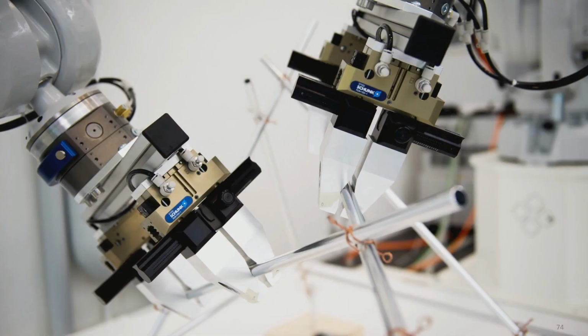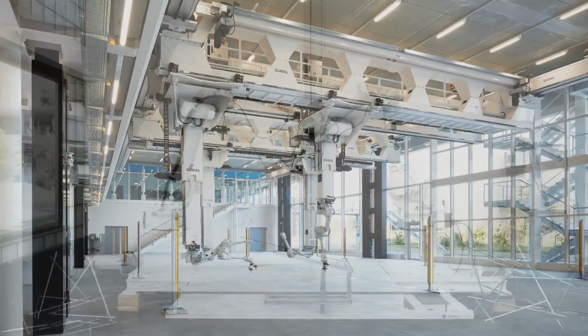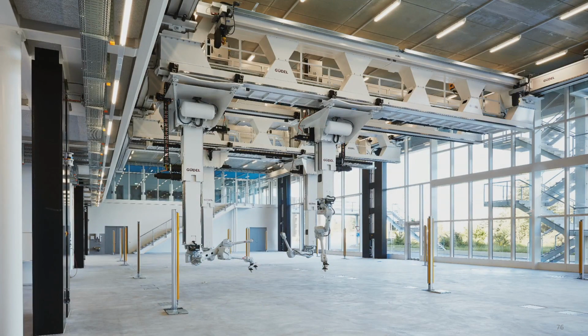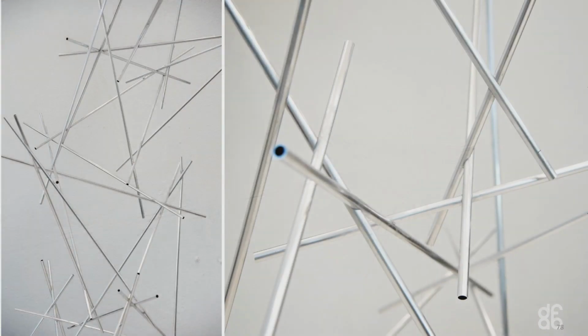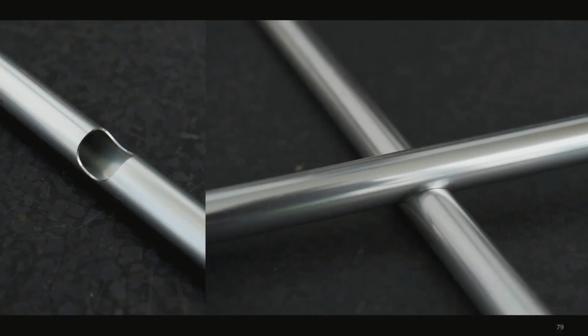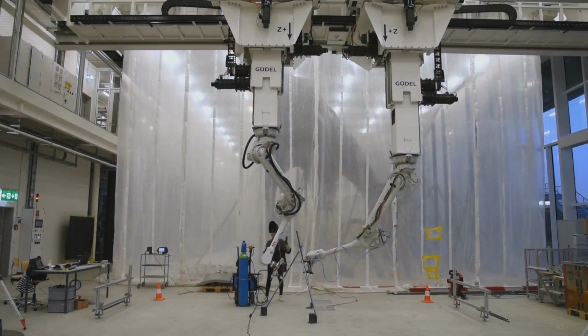With regards to fabrication, I used 2 robot arms, 2 different setups, a smaller scale one or medium scale one with stationary robots, and then the robotic fabrication lab again with 2 of the large robots working together. I tested different materials and connections, from aluminum with wires to glued connections that required a custom milled notch, and then ultimately ended up with steel and welding, basically because it simplified the process and it provided the necessary stability and stiffness into the structures through it.